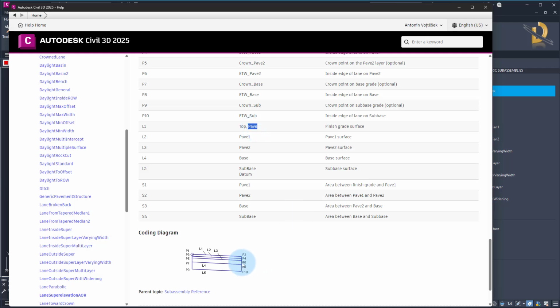While for other links, you want to display, let's say, ratio for cut and fills, you want to display 1 in 2, 1 in 3. While for the paves, you want to see 2%. This will allow you to do that because if the link has multiple codes, you can assign various styles to each code. And that's very important to remember.